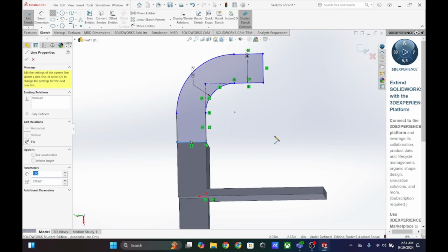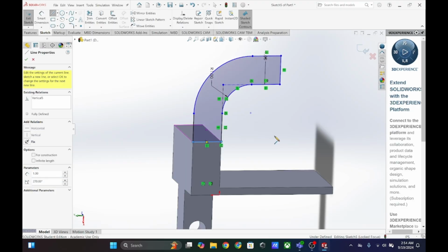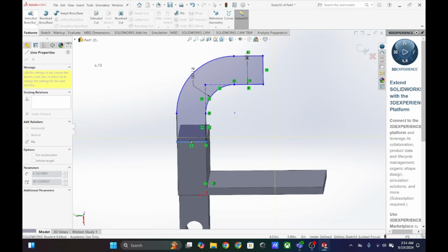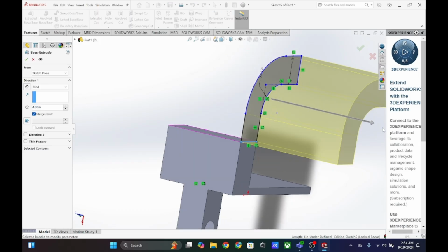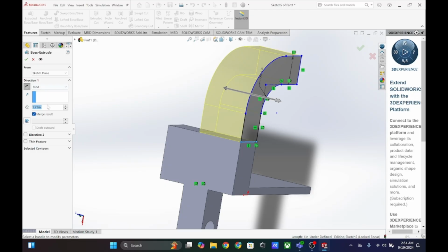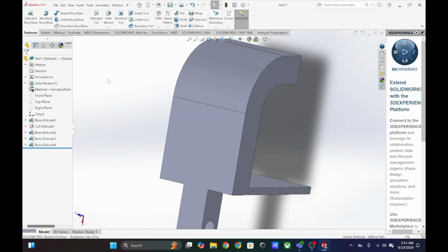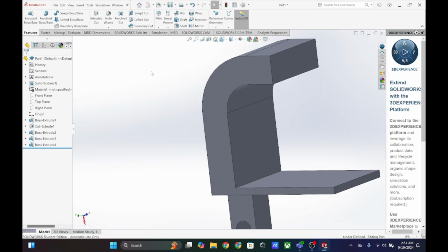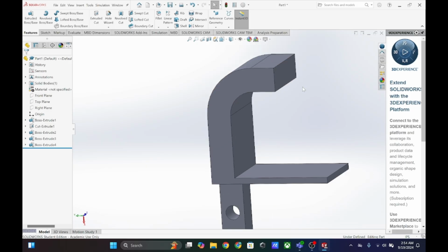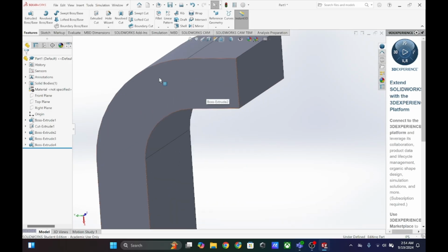Now the opaque blue is appearing. That means that it is solid, and now we can extrude it. So we're going to extrude it in this direction to be 3 inches across so that it fills it. Great. Now what we're going to do is cut a 45-degree angle from the surface of this.